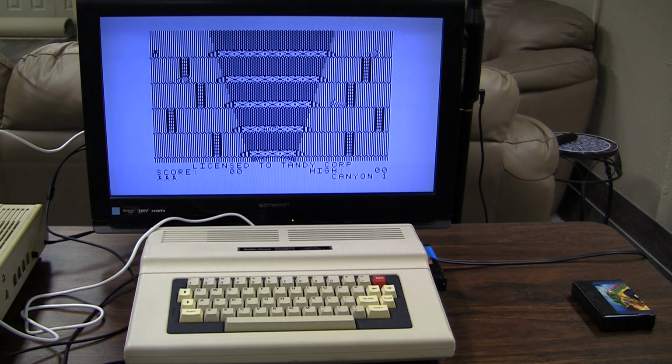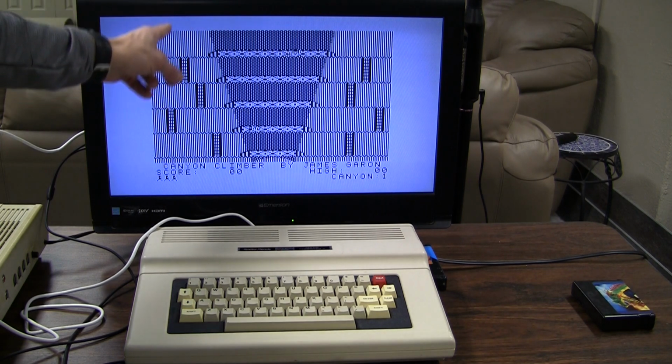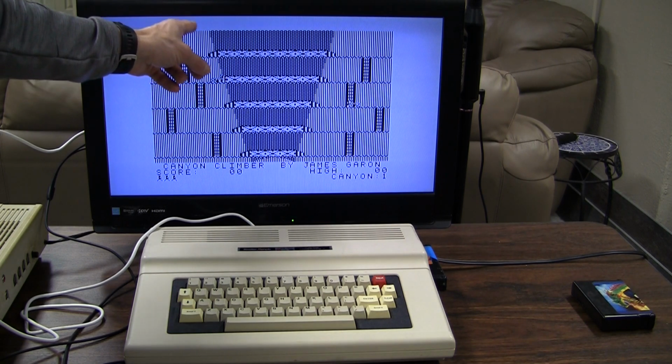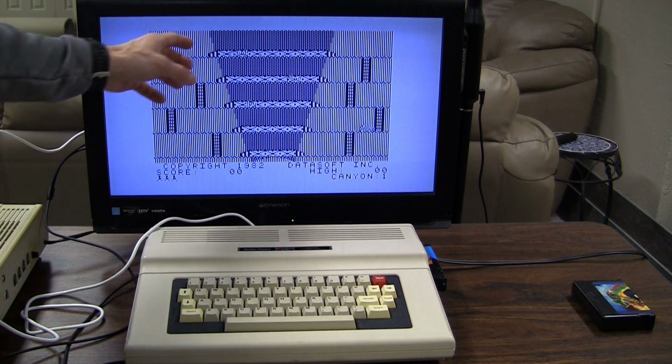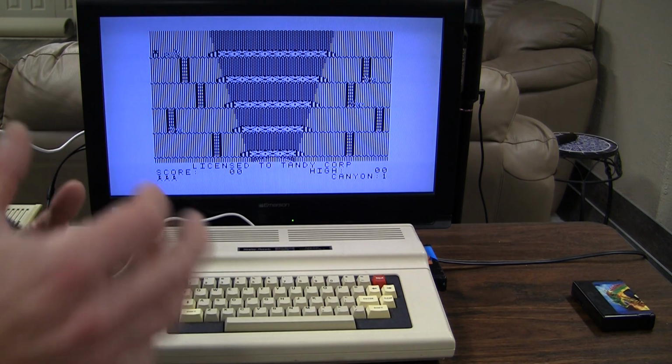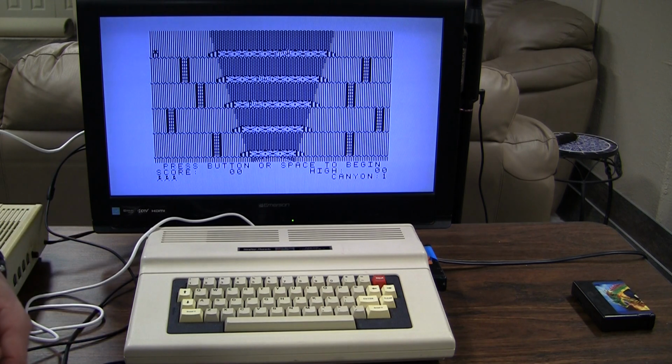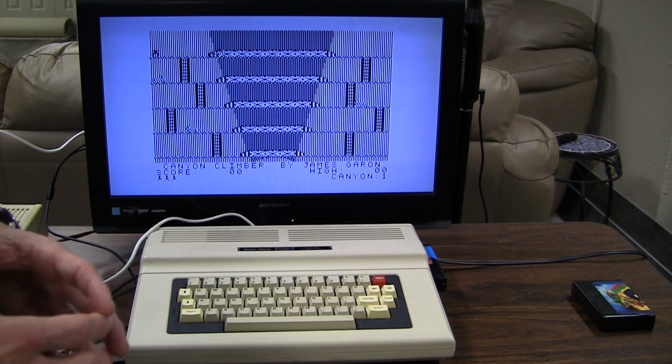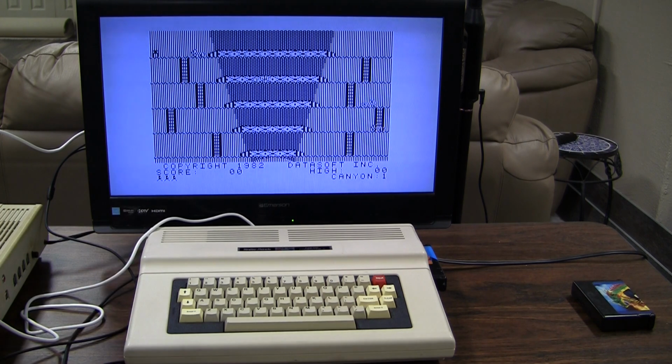And then it changed to this PMODE 4, and the striping is not able to produce color because it's not getting mixed. The chrominance is not getting mixed with luminance at any point in the signal chain. So the luminance and chrominance are separate all the way out to the monitor. And there's no point in there in which the artifacts can be generated.